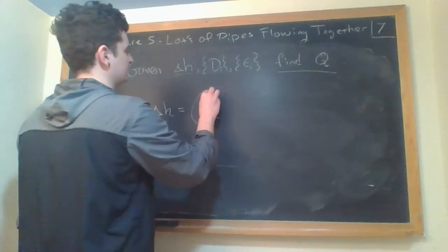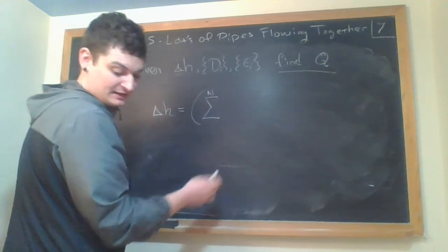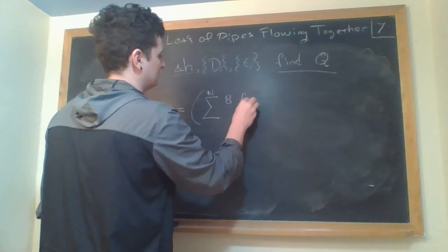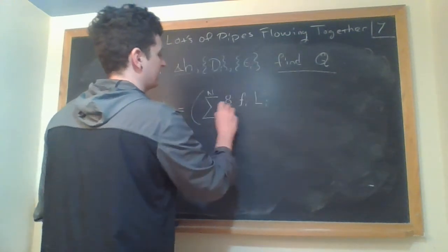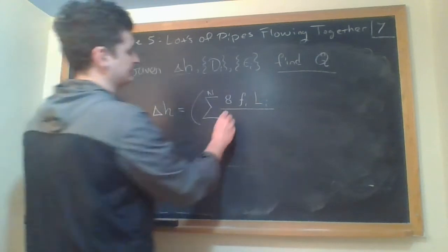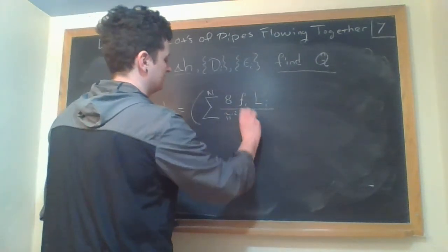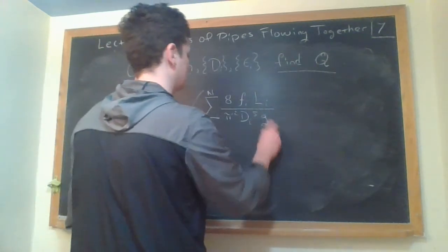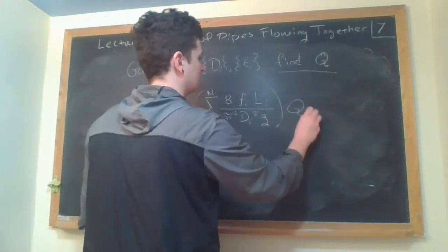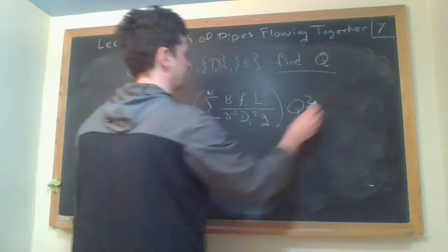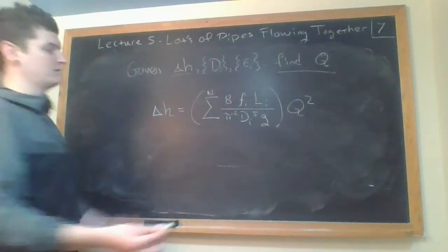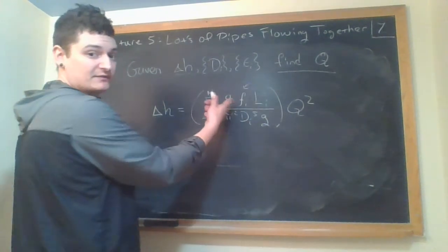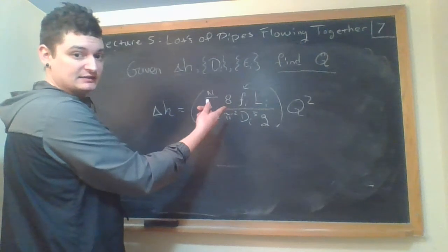You do this work to figure out all these effective lengths to write out this sum term, which is tricky because you have to keep remembering that each of these f's, right? You still write the same equation out for all these pipes in series. You just have to write, it's nasty because each of these f's have their own functions associated with them.